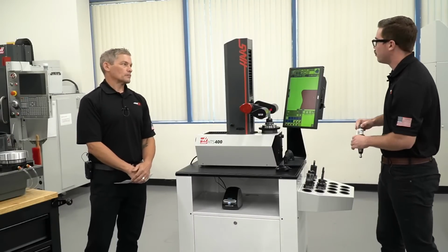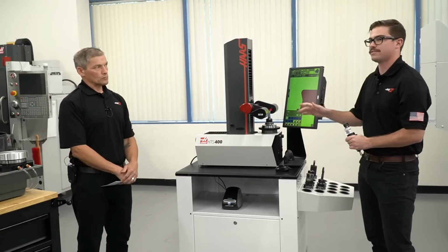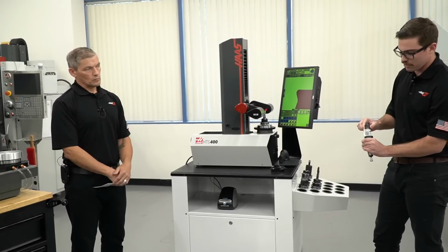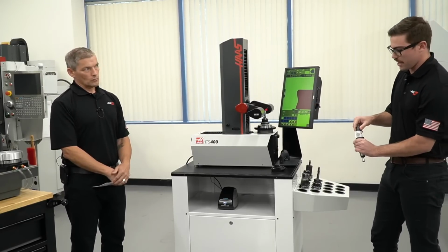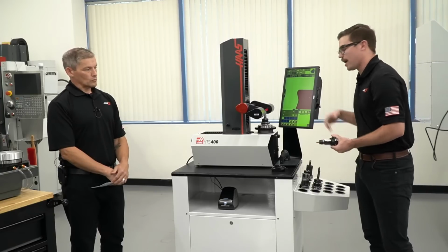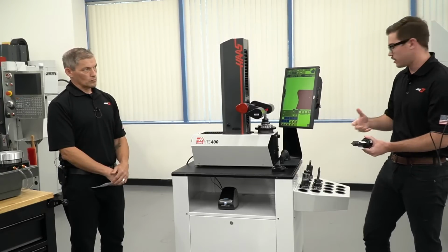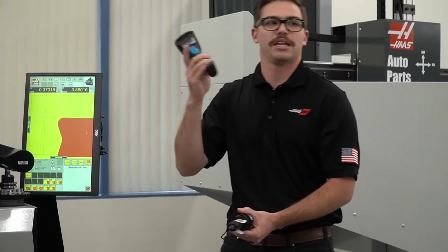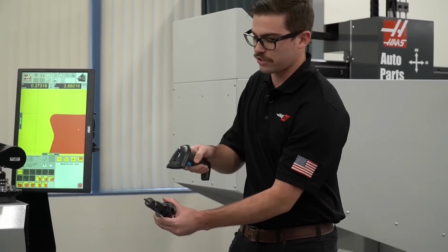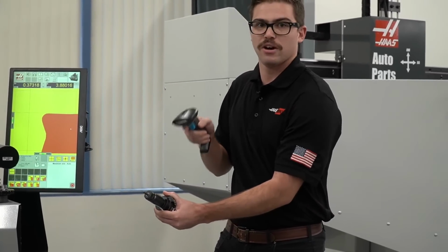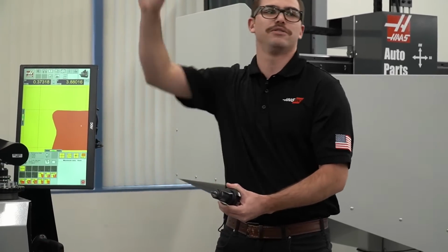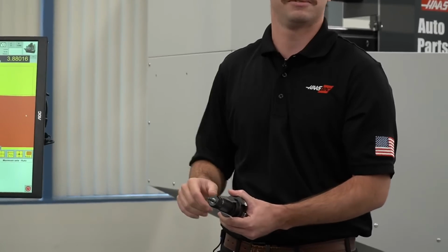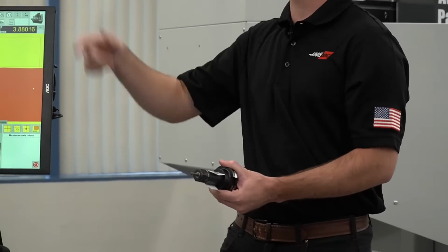And so when I create my tools and set my offsets, I can actually print out a label with its QR code. When I go over to the machine, I have a USB Bluetooth reader for the machine. I can take my QR scanner and go straight and upload directly onto my control, and it'll upload the offsets onto the machine. So I don't have to worry about exporting a file.